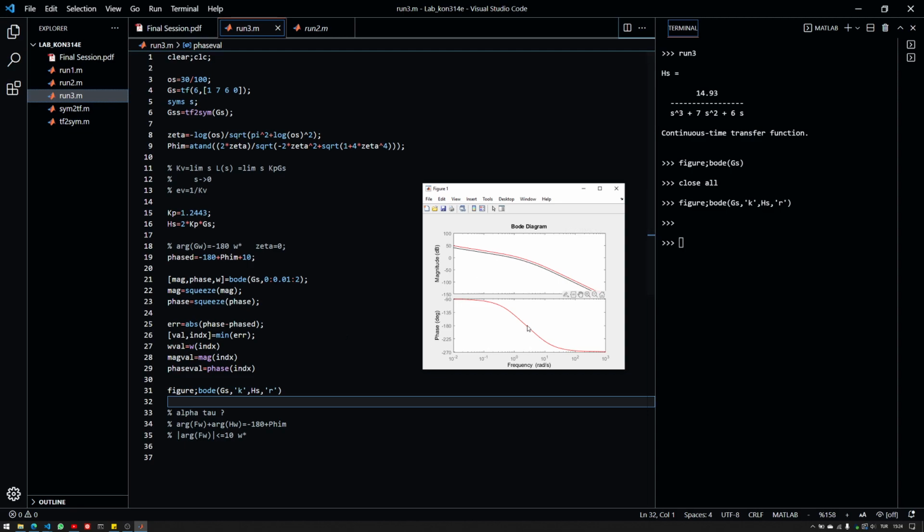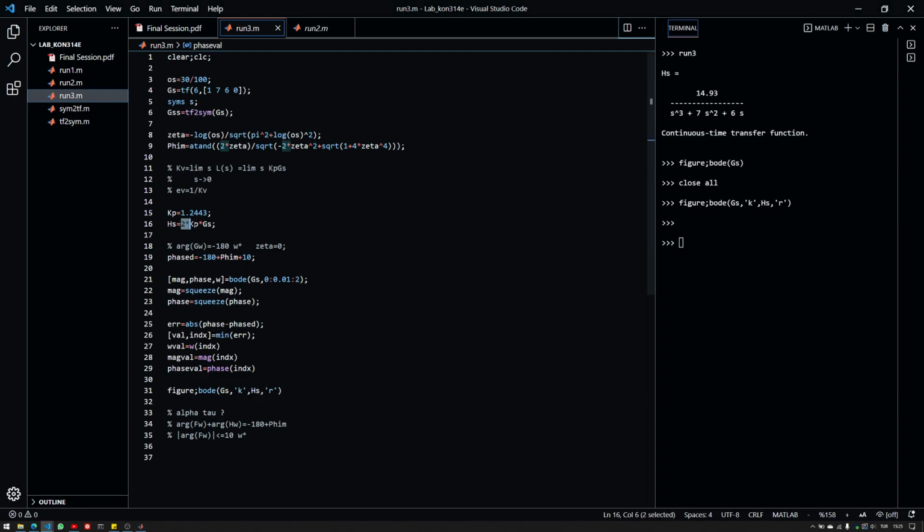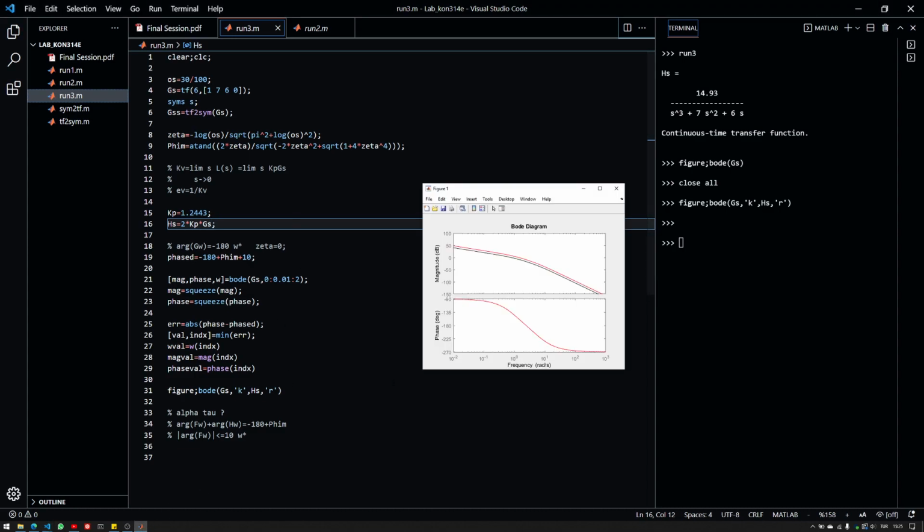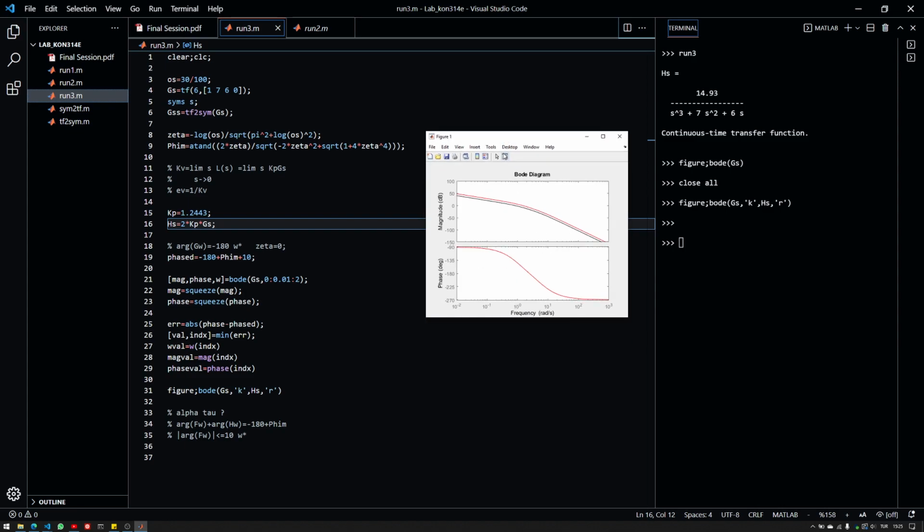So you can safely use the same phase plot and search for the frequency, but the gain value would be a bit different. So you have to take this part into account. Basically, you have to multiply by 2.4886. So yeah, that's the tradition. If you prepare an exam question, most of the time you require the student to see this kind of stuff.